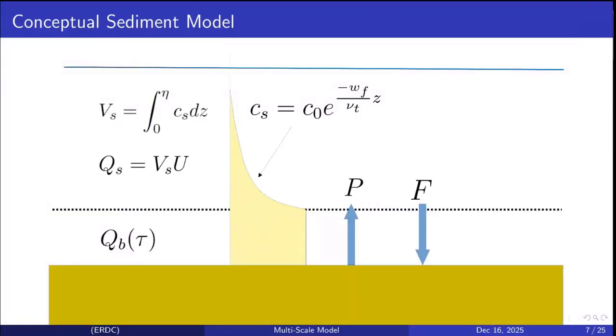the sediment transport problem. And there's a lot tied up in this slide, and I apologize for that, but let's just split it up into two regions. The region below the boundary layer, which is shown as a dashed black line. Underneath that, we've got a bed load that's being transported directly as a function of the excess shear stress, which I'll cover in a second. Above it, it's a little bit more complicated.